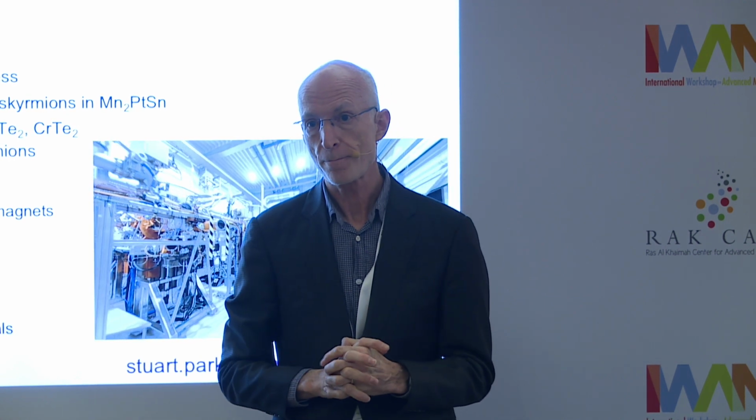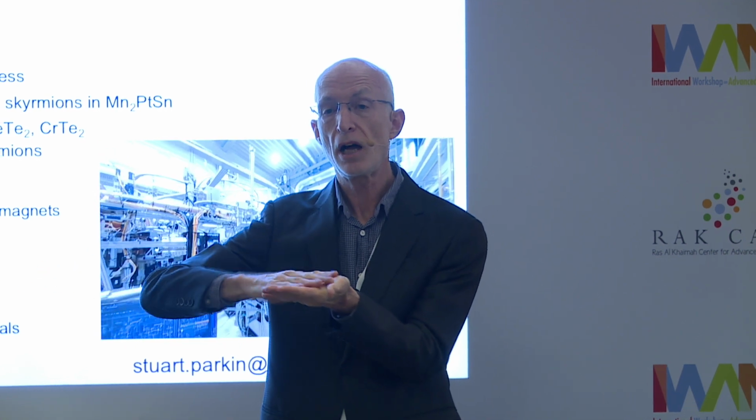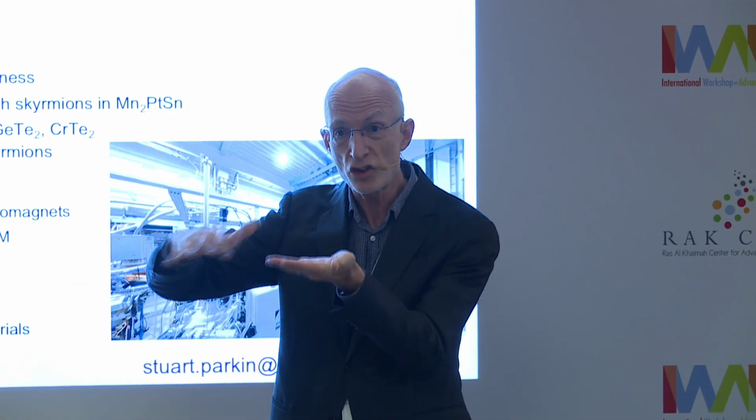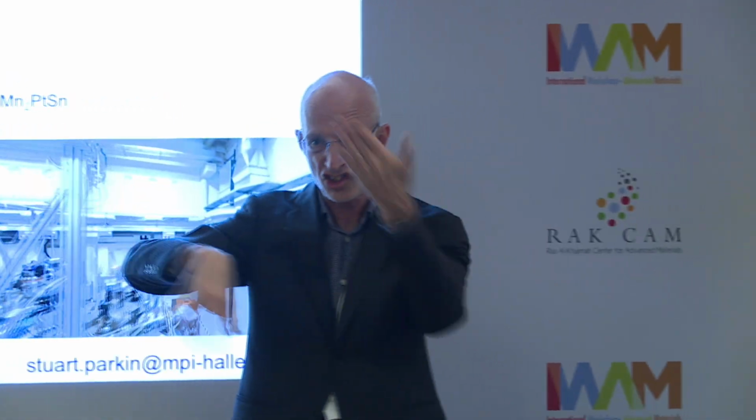So it's destructive like a ferroelectric memory? Not destructive. Totally non-destructive. The domain walls are moved by current. They move. You don't destroy the domain walls. The principle is they can be moved backwards and forwards without destroying them.